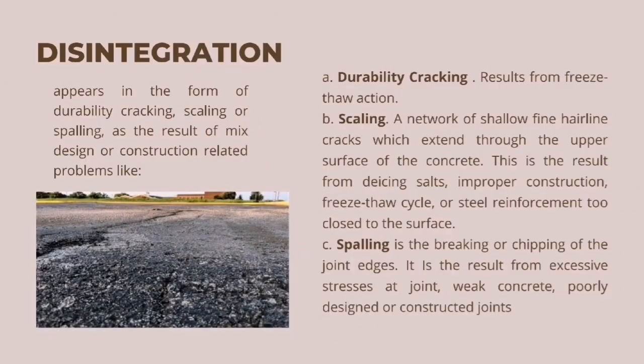Disintegration appears in the form of durability cracking, scaling or spalling as the result of mix design or construction-related problems. A. Durability cracking results from freeze-thaw action. B. Scaling, a network of shallow fine hairline cracks which extend through the upper surface of the concrete.